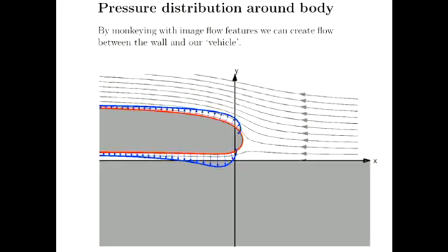It's being sucked downwards. So this is something that F1 cars will frequently use. They'll try and maintain a very narrow gap between the vehicle and the road, and that generates a large portion of the downforce that vehicle needs to corner, okay?